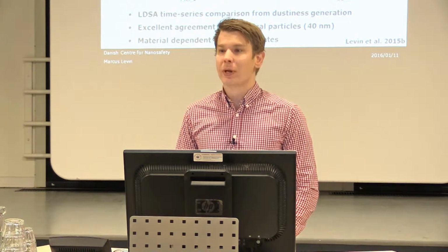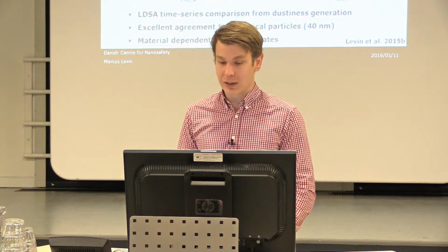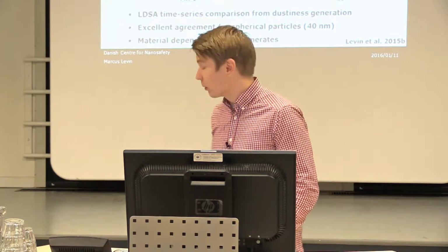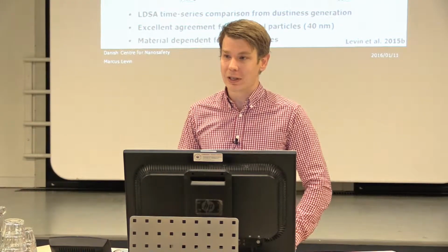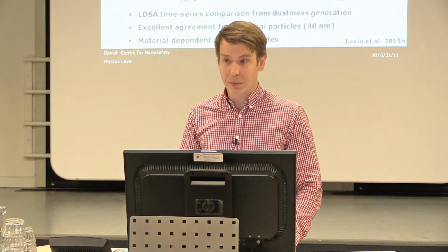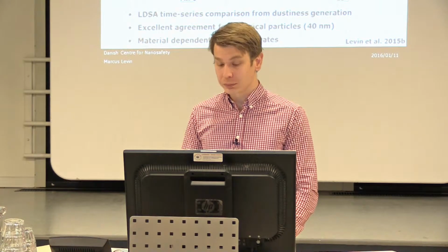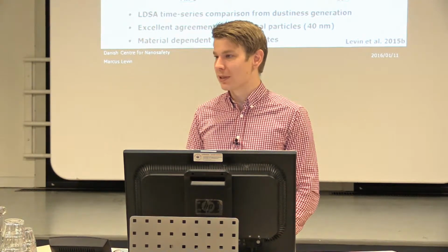But if we then look at the more realistic powders, we can see that suddenly there is quite a big dependency on the particle type and the material type. And this here is a logarithmic scale, so the difference in measurement between the different instruments is actually quite big. For some types of materials, we can be 10 times higher for some instrument than the other. So it's a little bit hard to directly compare these instruments. And this is why it's important to remember that our exposure measurement might actually be dependent on what instrument we go out and measure with.